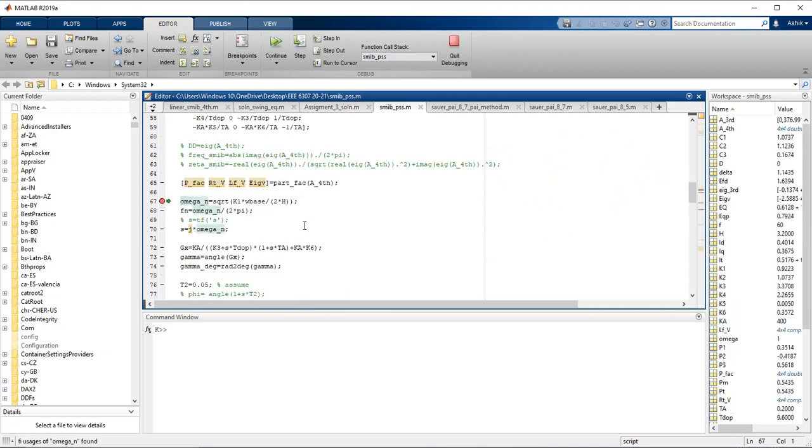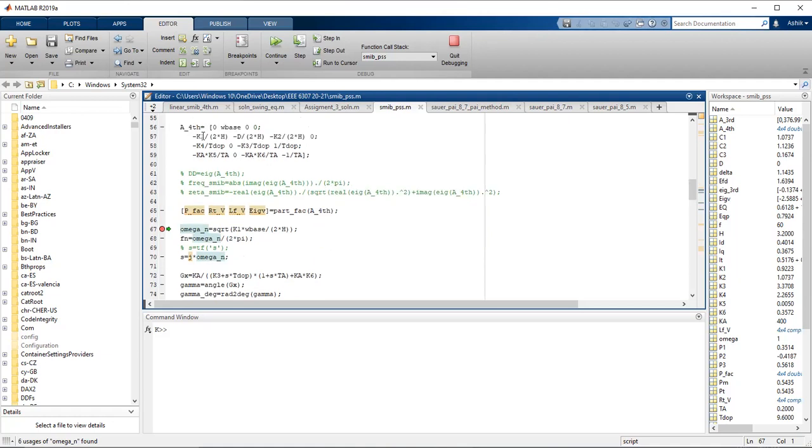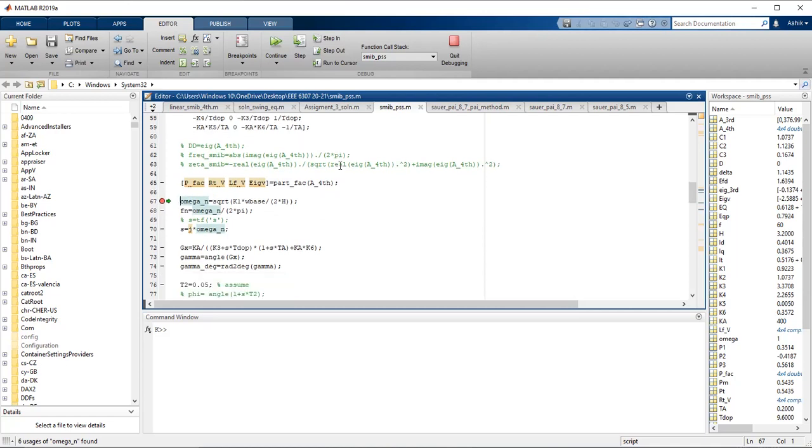So if we continue up to this point, okay, let's see the participation factor. This is the fourth order system. So this is a 4x4 matrix, and that is being built here after the incorporation of the exciter. These are the eigenvalues. So you have 4 eigenvalues. Now you have 2 complex pairs. Okay, so there are 4 eigenvalues, but again you have all the real parts negative.